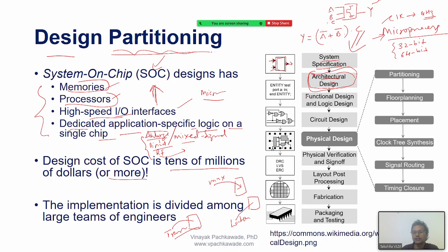So this is the functional design, and then the logic design, just like I explained: how many muxes, latches, transmission gates, adder and subtractor circuits and all that. Once I know that, I go to the next stage, circuit design. This is how the circuit design looks. I know the logic function, and then the interconnection of gates will happen.